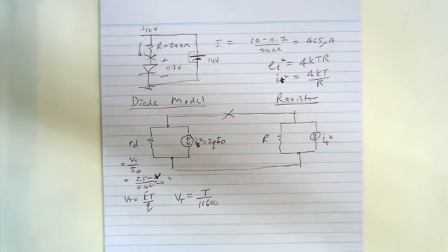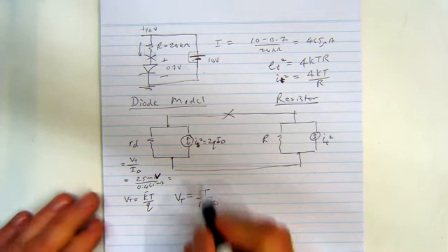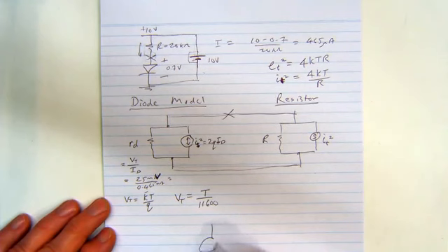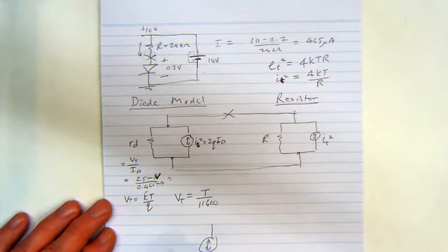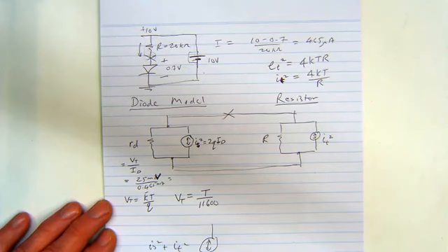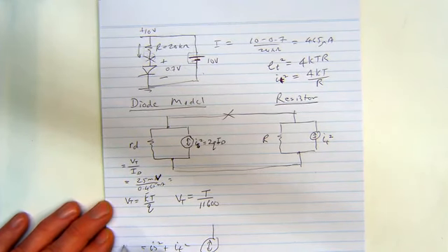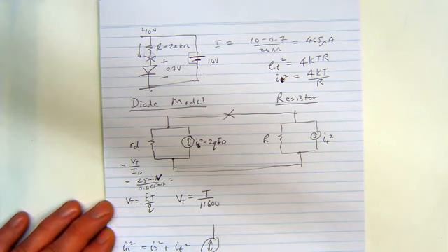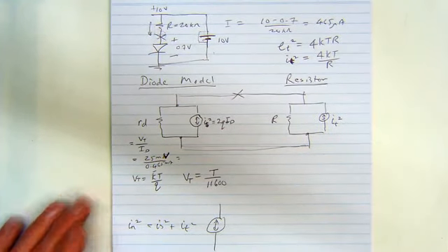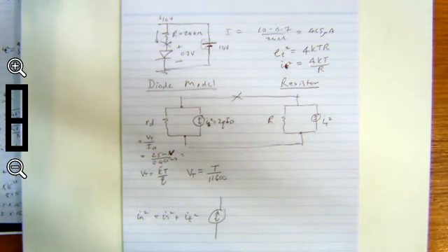So what happens next? Consolidate the two resistances together and the two currents together and find out what voltage arises as a consequence. Can we put the two current sources into one? We'll call it IS squared plus IT squared. And now I'll just use the overarching line in here, and I'll back that off so you can actually see it.